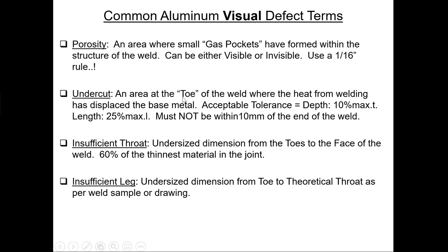And the toe of the weld, where the weld intersects with the base metal, has a little bit of a groove in it. Now, there's maximums. When it comes to the depth, we have gauges we can use to measure it. If you're a structural company, you would probably have depth gauges to make sure that undercut met a certain criteria. They actually make good gauges for it. And of course, we could stretch out a tape measure and talk about whatever the length is, right?